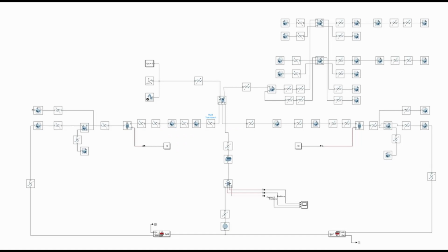and the ball. We used the Simscape Multibody multiphysics library to import the CAD files of individual parts of our robot. We had to then manually connect all the CAD files to each other to assemble the mechanism with all the joints digitally in Simscape. We used the Simscape Multibody contact forces library to simulate the forces between the bodies. The library had a tube to sphere contact force block which we used to accurately simulate the contact forces between the spherical ball and the cylindrical wheels.